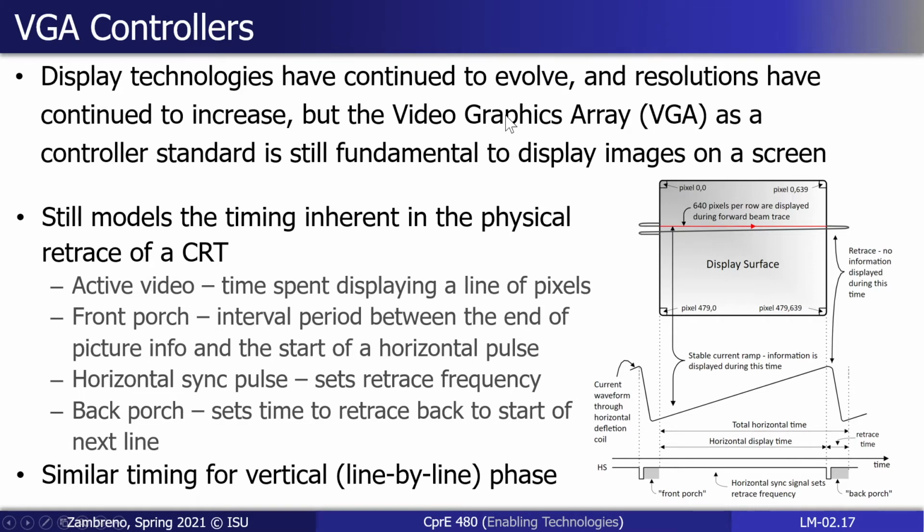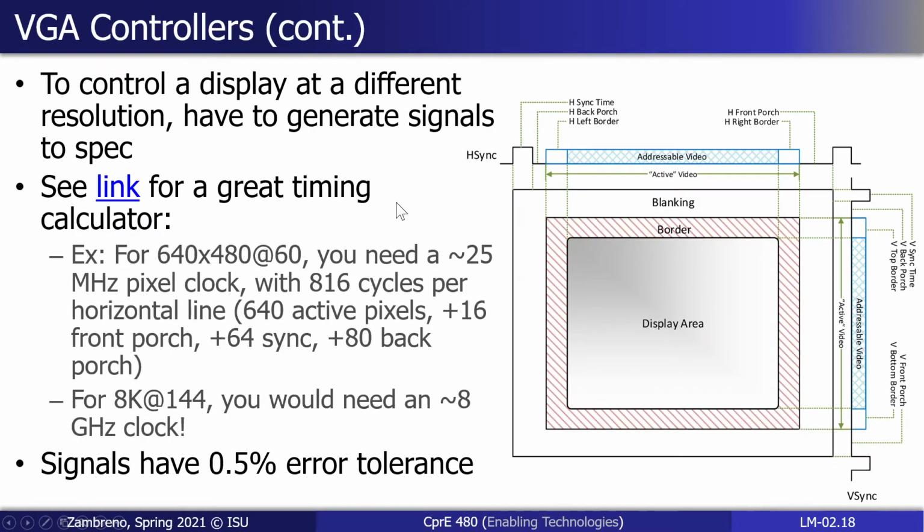And so when we talk about the difference between a 640 by 480 VGA cable connected to an old school CRT monitor, or even things more basic like composite video cables, versus a 4K display refreshing at 120 hertz, the main difference is the size of those pulses.